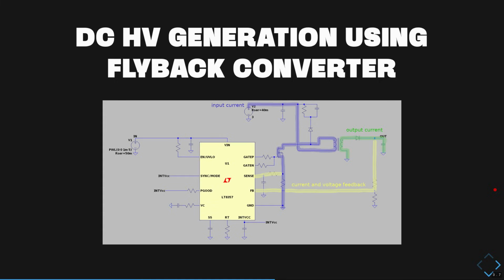Basically, you have an input current that's going in here, and that's controlled by this MOSFET. And whenever the current is switched off here, the magnetic field in the transformer dissolves itself through the secondary loop, through the output current, and charges this capacitor here. How does it work? There's this controller chip.